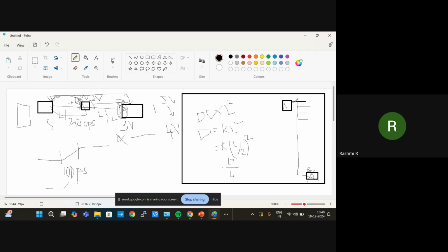From the top of this chip it is driving some cell at the end. So it will be difficult for this cell to drive this long, right? So we will duplicate the cell, same cell A here, and we will connect this net directly to this.